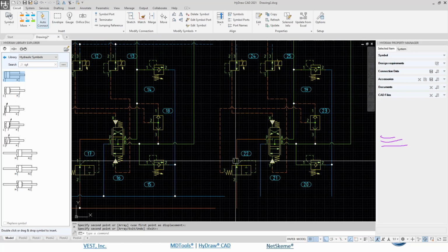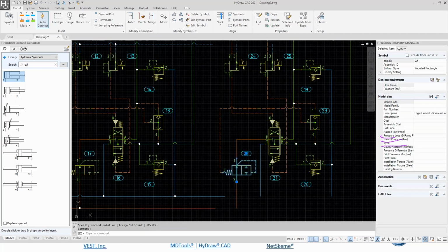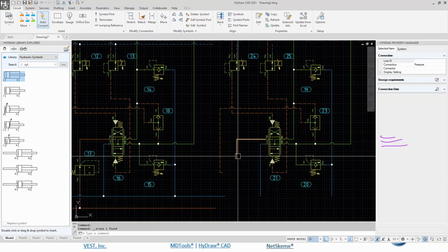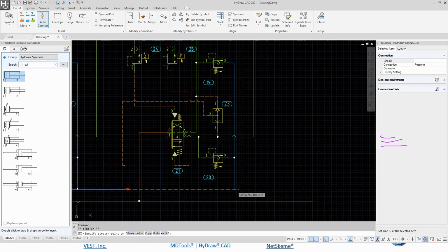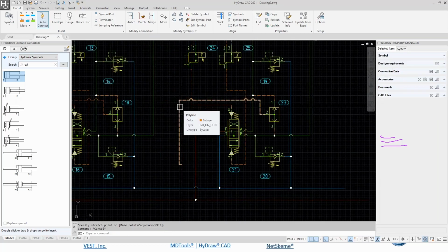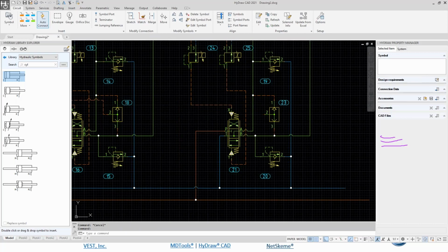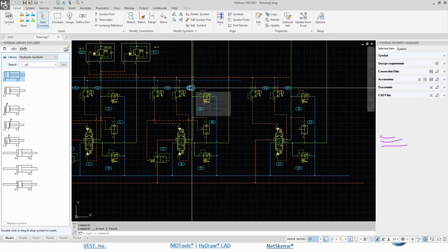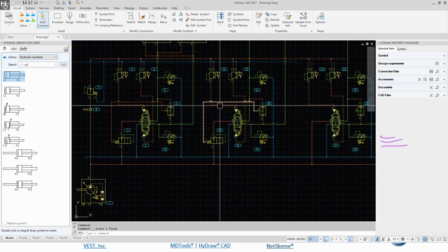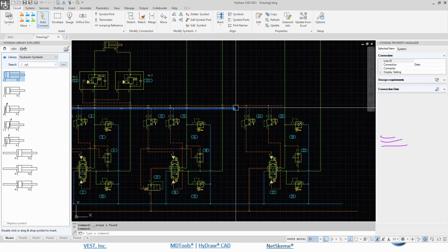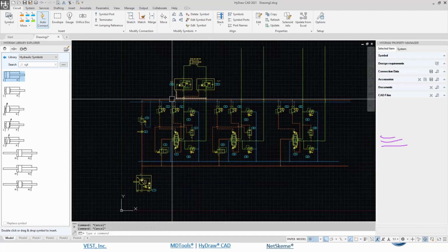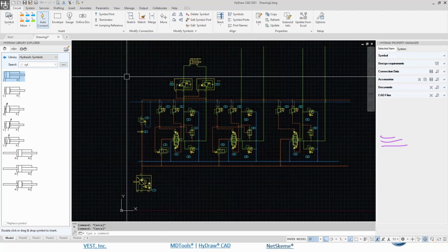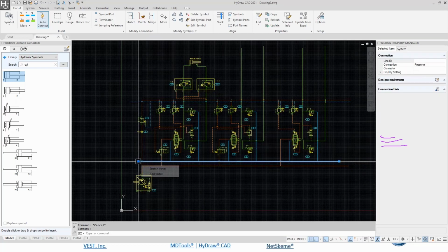And maybe here we don't need the pressure compensator on top. So we just remove that line. We take this straight. Also this one, we go straight. The shuttle valve will be needed in any case, so I will take it because later I'll need to select the signal to go back to the pump. And by the way, my connection is now made properly. Let's say that all this is represented by something like a manifold. So let me draw a rectangle.